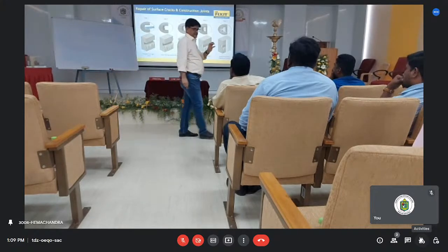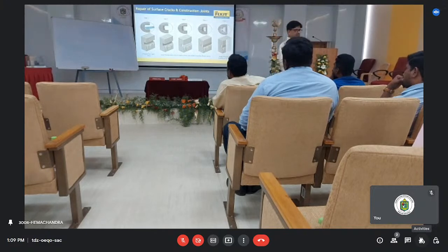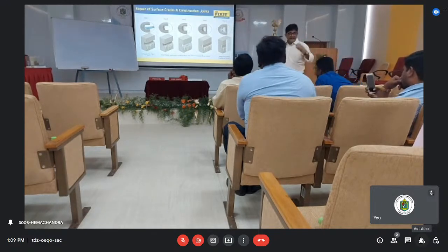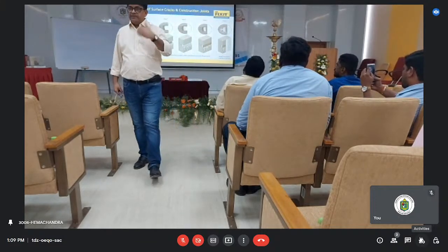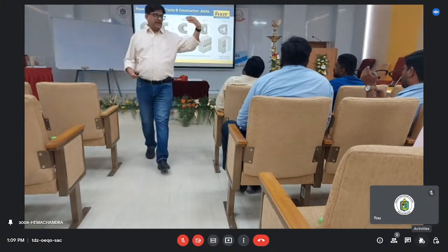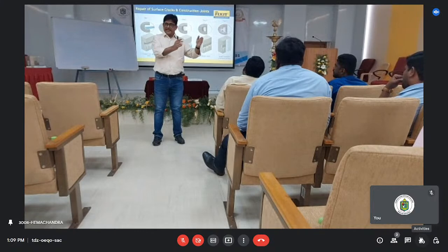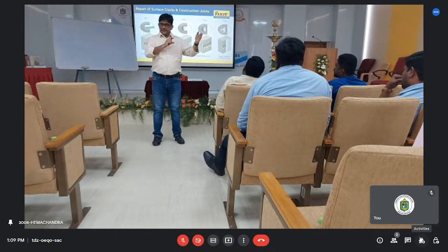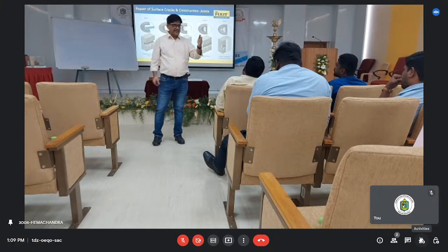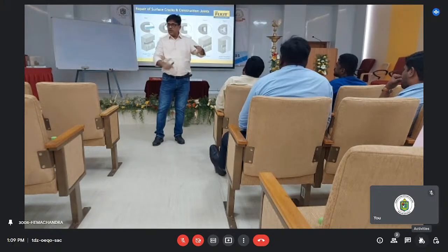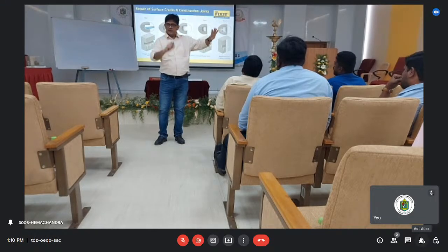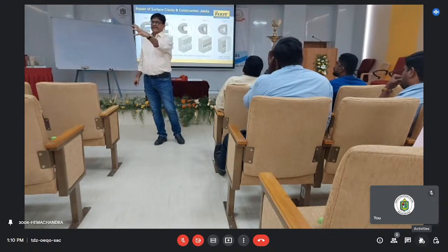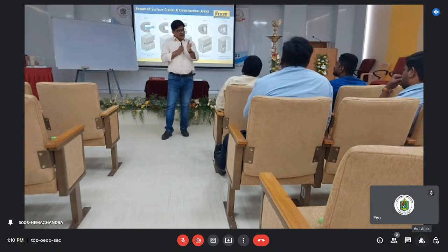What will be different? This material, when it is there, will remain present for any water. You may have given a water stop there, or may have missed out the water stop. Whatever treatment you give, you cannot reach the positive side. You are doing everything from the interior. If I only seal with cement concrete or something like that, it may shrink again tomorrow, because your entire construction joint is still open. You are only working on the face. So water can again come in and through the cement concrete come out again. Why are we using a crystalline putty?